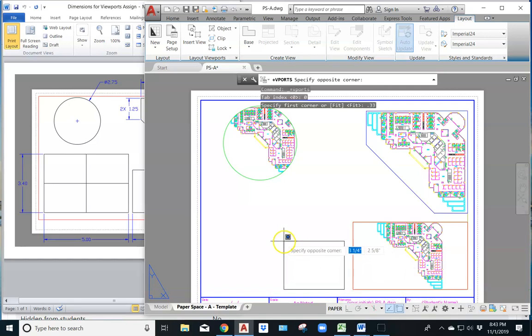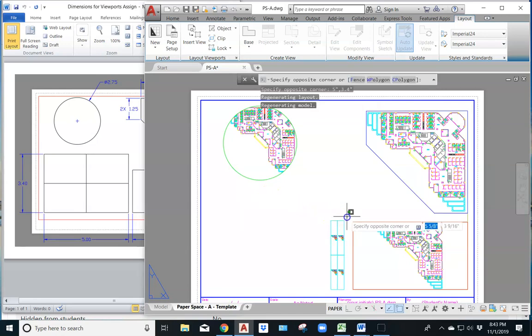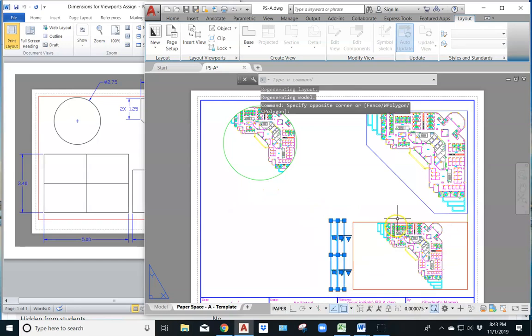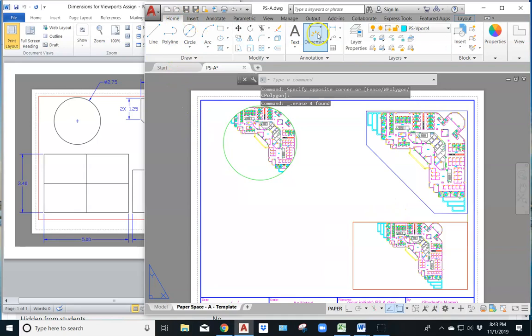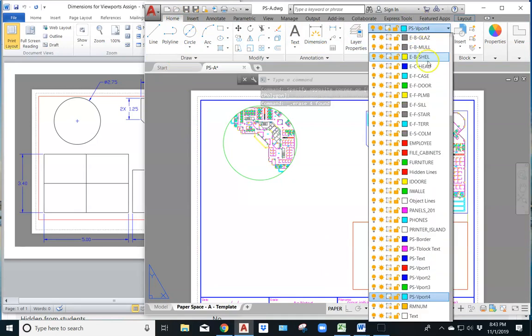And then I'm going to go ahead and go up. Let's see, I want to go over 5 inches, I said. So 5 inches. And then up 3.4 inches. And just a second. Oh, I forgot. That doesn't work well with the rectangles. That's why we drew the construction rectangle for the other one. So I'm going to do the same thing here. Go onto my construction line layer.